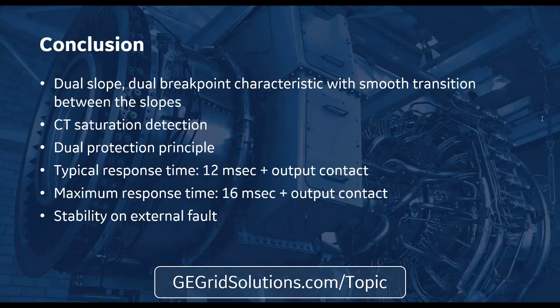For those that are all confused, a lot of systems today are going with low impedance bus differential over high impedance bus differential. And I'll give you 2 quick cases. First is I've got a customer in a paper mill, and they had a high impedance bus differential scheme. Well, everything was fine, but one day it tripped. Making a long story short, it turned out when the system was set up, one of the CTs was wired backwards. And unfortunately, in a high impedance bus differential scheme, all the CTs are paralleled. Right.